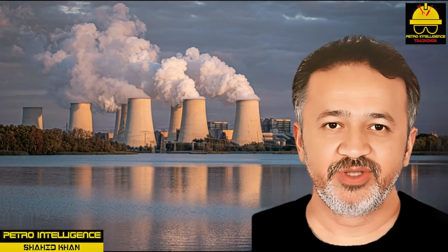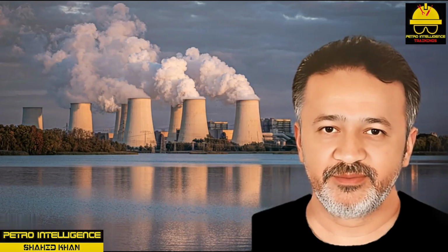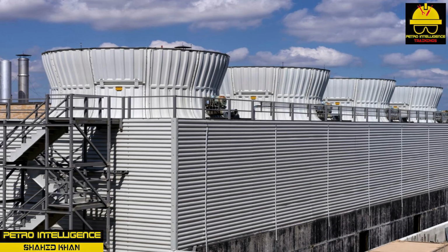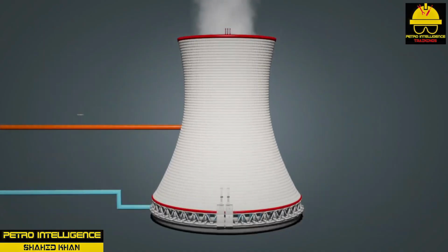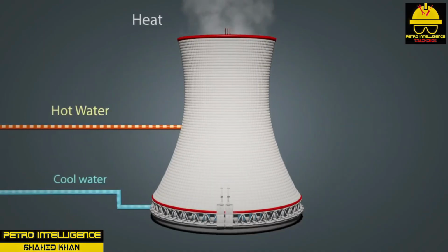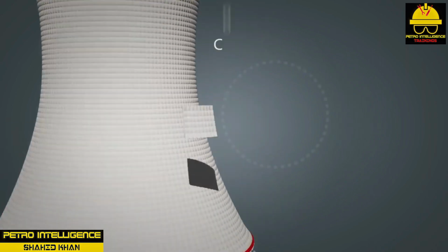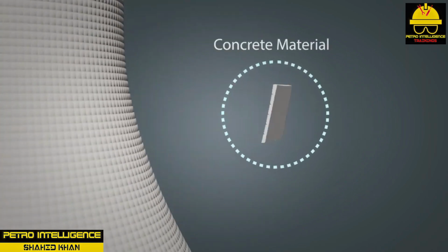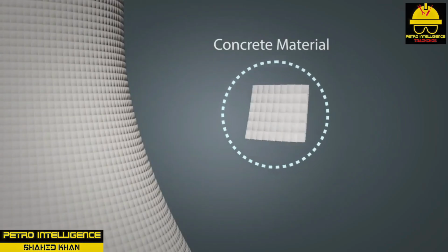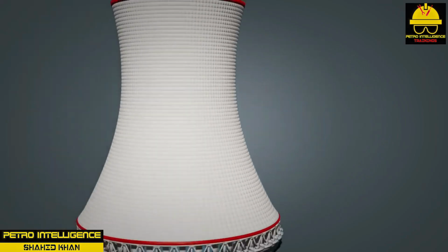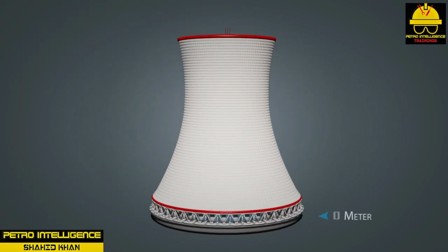Cooling tower applications and theory of operation. Cooling towers, as shown in picture, are heat transfer devices designed to cool water for reuse. They cool hot water by bringing it into direct contact with air, using countercurrent or crossflow patterns. A cooling tower contains wood or plastic slats, called fill, that direct airflow and the flow of water falling from the top of the tower.